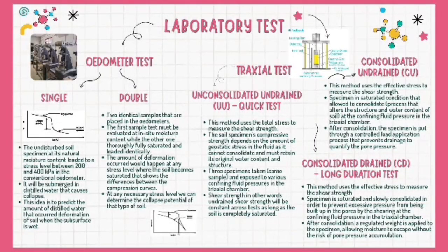For laboratory testing, a collapsible soil laboratory test examines whether a soil sample has the potential to compress or collapse when it is saturated with water, and it is particularly crucial for loose, unsaturated soils like silty sands. If this behavior is not appropriately handled in the design, it may result in structural damage. Two common conventional laboratory techniques are the oedometer and the triaxial techniques. Both take into account important factors that govern the densification of the majority of soils after soaking, including the dry density, the initial water content, and the applied load.